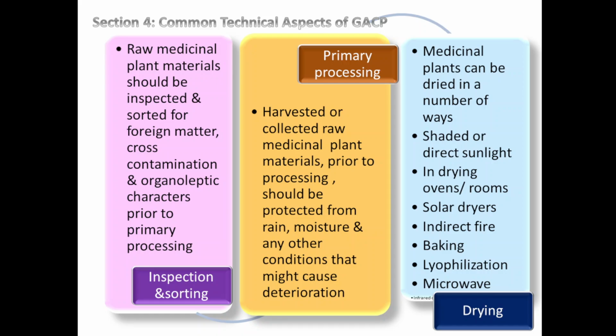Lyophilization is also known as the freeze drying process, and it removes water from frozen material under vacuum. Vacuum is applied, and due to the application of vacuum, whatever water content is present in the frozen material is removed by lyophilization. This technique is used for materials which are heat sensitive and cannot withstand higher temperatures of heating. In that case, the lyophilization method is used for drying.